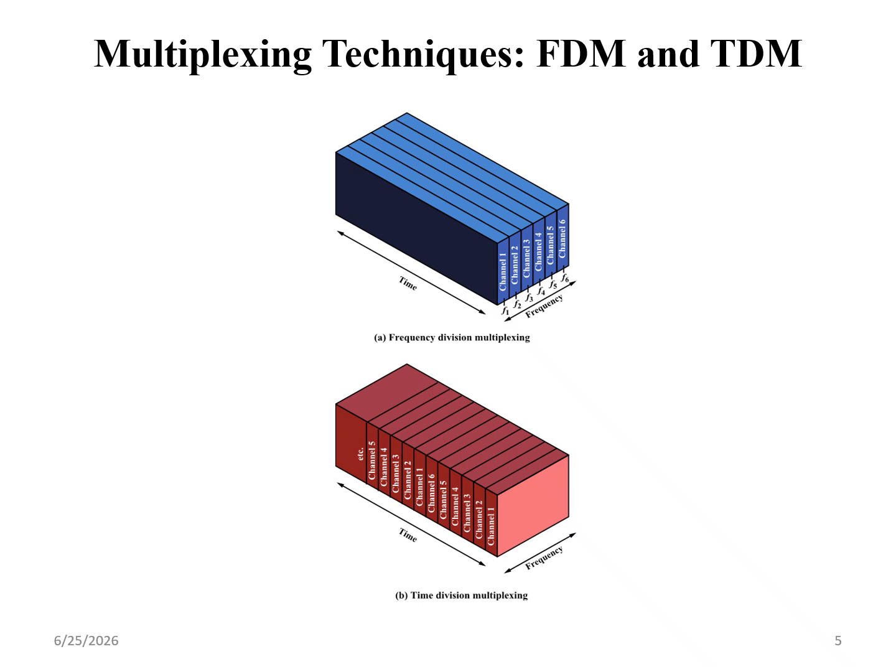The same is carried out for time division multiplexing: x-axis frequency, y-axis time. The only difference is that for each and every user in FDM, a frequency range is given, and they communicate to the receiver. In time division, a time slot is given, and they use the medium or channel.